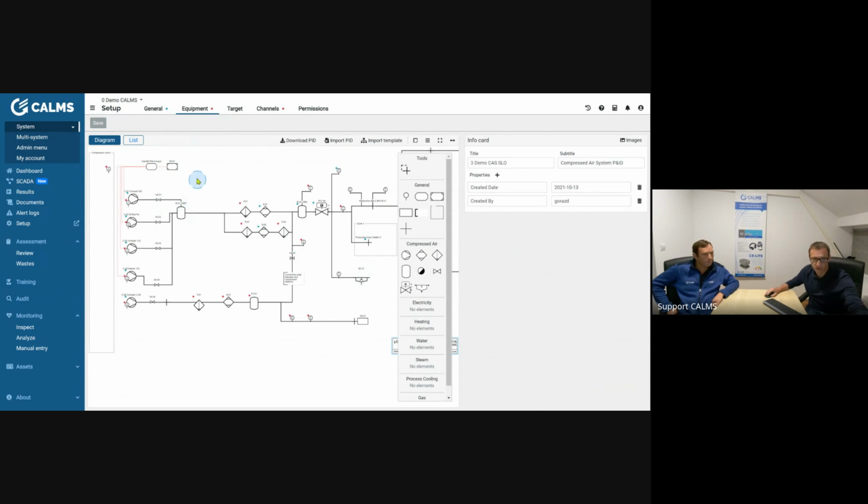We will install one device here in the compressor room. Here you see this is one device, which will collect the amps from each of those compressors. Another one we will add in this room because it's not very close. I mean, it's 50 meters, but it's still too much, so it's easier to connect a third device, maybe. Okay, but this is a new compressor, and it's 160. It's written on the box. Yes, but still we need to know how they operate together with the others. Maybe you can make the control better. And one in zone 1. I really need the pressure, and here we will put one pressure sensor with another device.